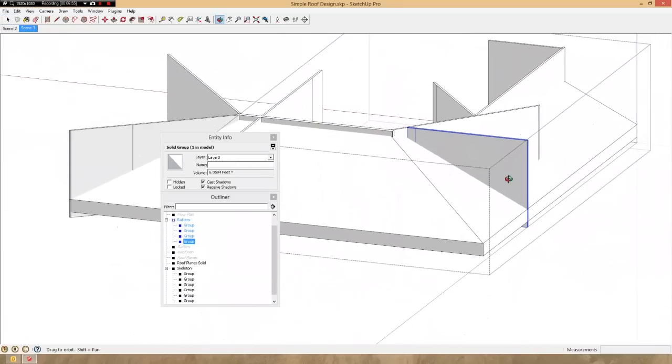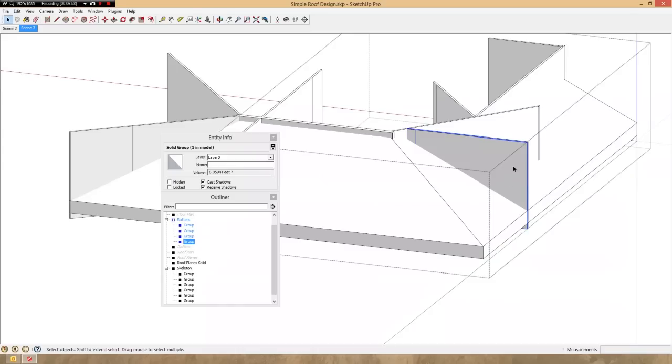I'm going to show you a method to do that that is kind of manual. There is a better way to do it. The way we're going to do it is with the tools that Sketchup provides you with the free version of Sketchup, Sketchup Make. If you decide to purchase Sketchup Pro, which is what I have, they have another set of tools along with many other features called the solid tools, and in them is a tool called the trim tool, which allows you to easily trim these things without having to go through the nosebleed that we're going to go through right now. But even though it's a bit of a nosebleed, it still works pretty well.